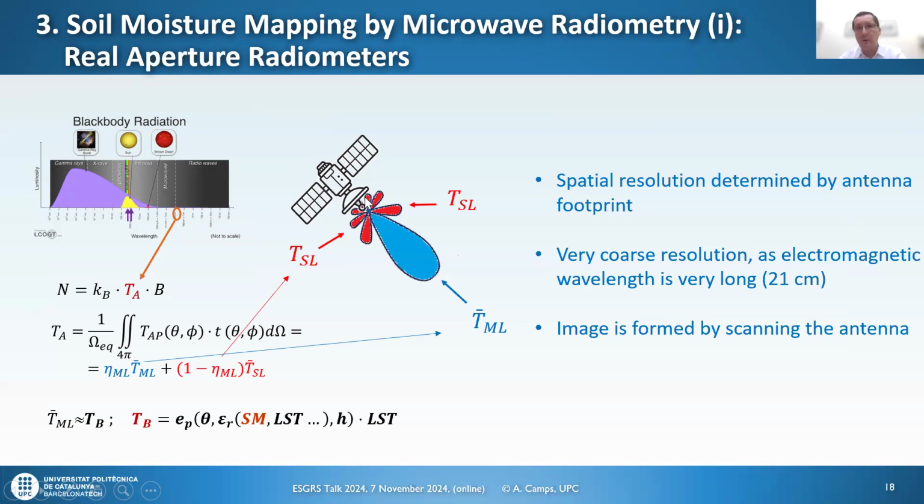So basically, the first thing is this amount of noise. Recall that the radiometer is like a radio, okay, and we measure the volume of this noise, no? This noise that looks like this, okay. We measure the intensity, the volume of this noise. So we not only have to remove the contribution of the noise that is generated internally in the receiver, because imagine that we disconnect the antenna and we still listen to the noise. So we need to subtract this contribution, but we need also to subtract the contribution from the side lobes, okay, to get the information from the main lobe.